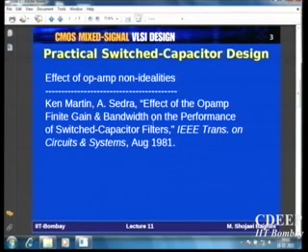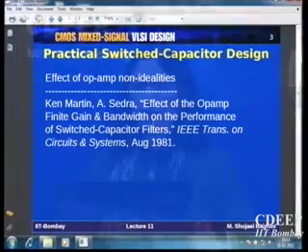So the whole concept behind switched capacitors was that we will get rid of the problems with process variations. We will also have very nice programming capability, and everything is controlled by the ratio of capacitors. Of course, by changing the sampling frequency, specifically increasing the oversampling ratio, which is the ratio of sampling frequency to the maximum signal frequency, you will get a better approximation of omega T much less than 1.